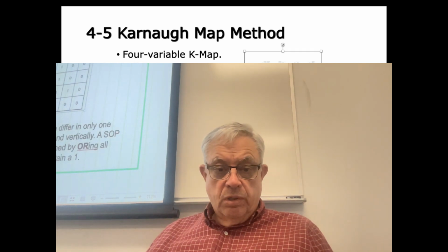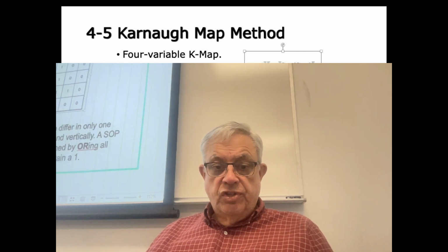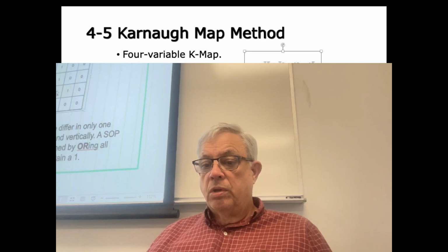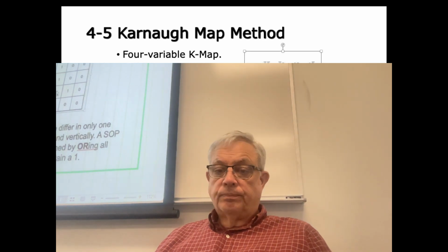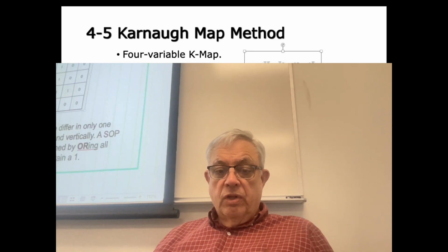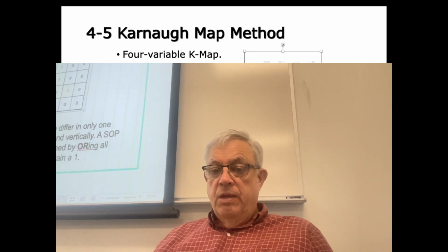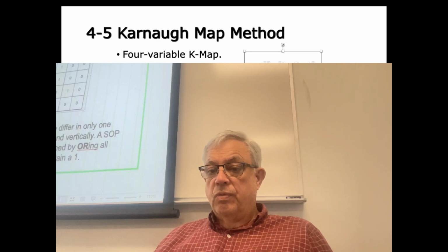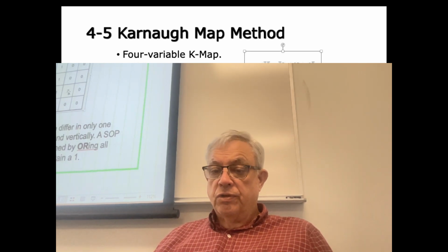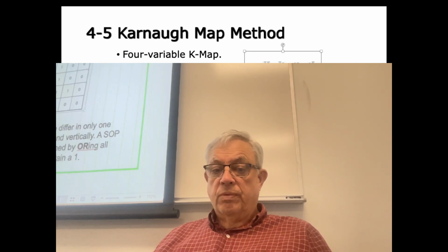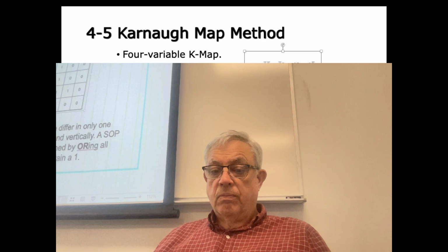And now I want C is a 0 and D is a 1. I put a 1 in this column. The last one I'm looking at is A, B, C, D. They're all 1s. A, B, there's 1, so that's this row. C, D, that's this column. So the intersection's here. So now I have 4 cells that have 1s in them from the truth table.